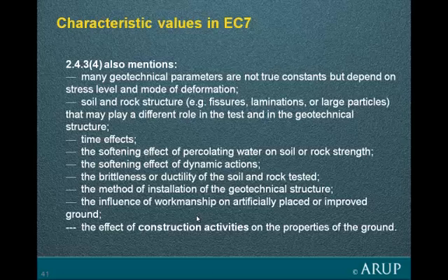We're also told that in this cautious estimate that we have to make, we have to think about the fact that many parameters are not true constants. They depend on stress level. We have in soil and particularly in rocks, are there fissures, joints that have to be considered? What about time effects, softening, brittleness and ductility? The method of installation of the structure, effect of workmanship, and generally the effect that the construction activities may have